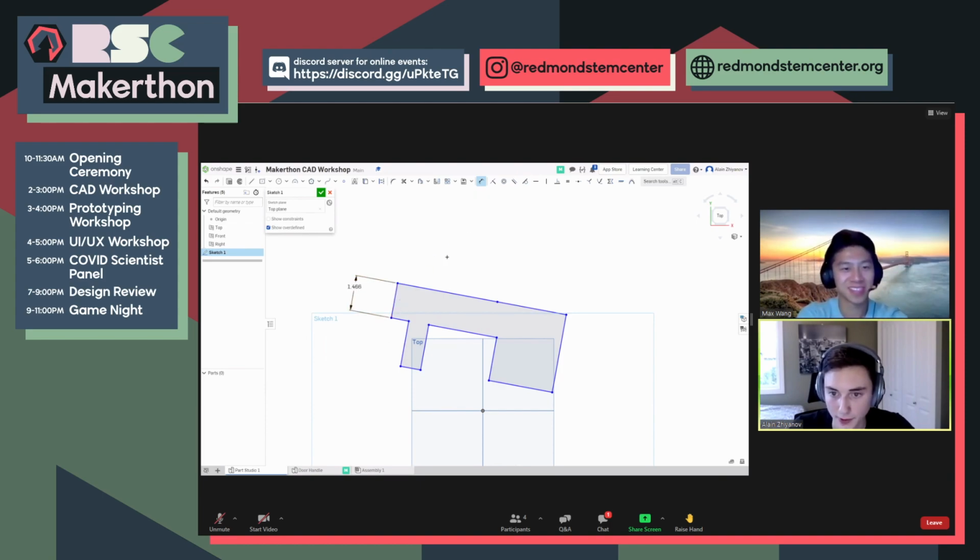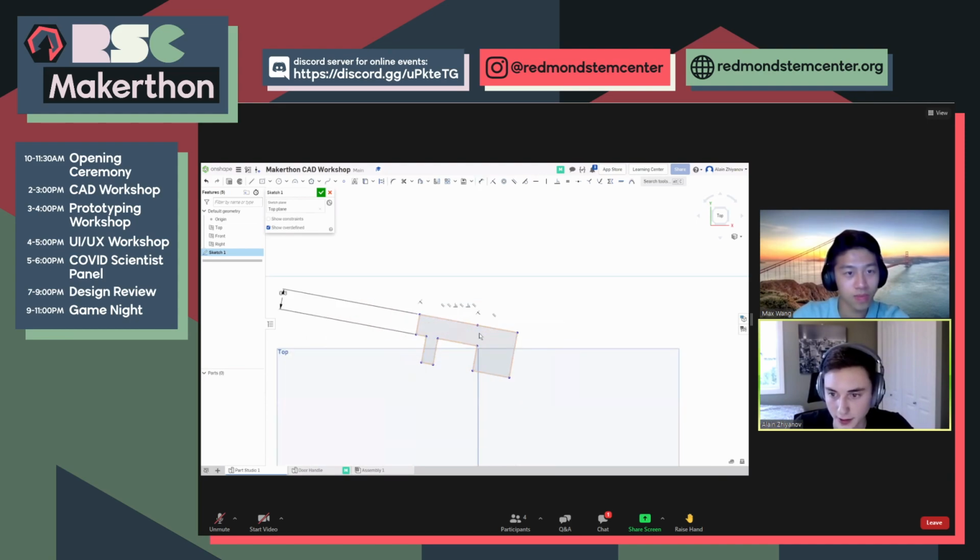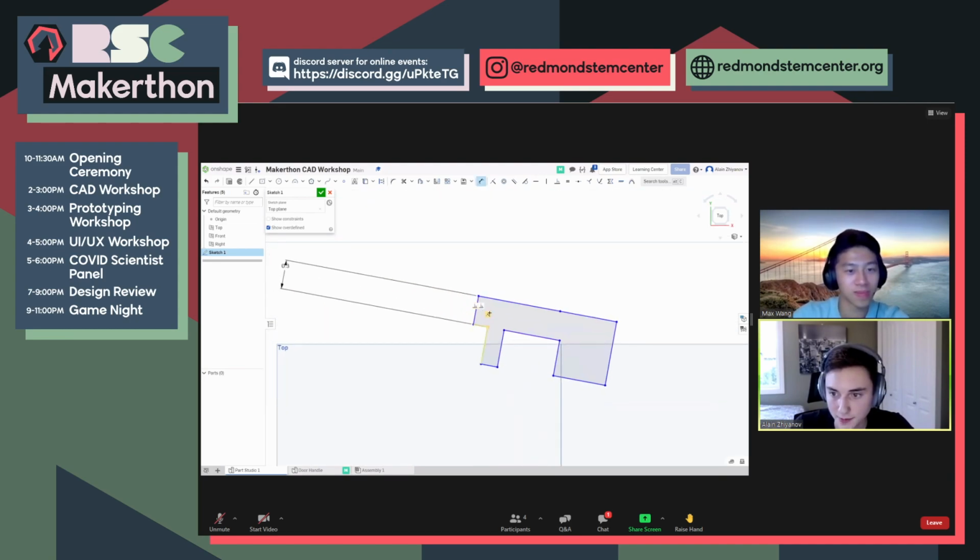What I just did, by the way, was I clicked on the line. I just dragged out and I clicked, and then it prompts me to select a dimension. So I'll go ahead and put in, let's say, 0.3 inches, right? And see it got a lot smaller. I can go ahead and just keep constraining these things.